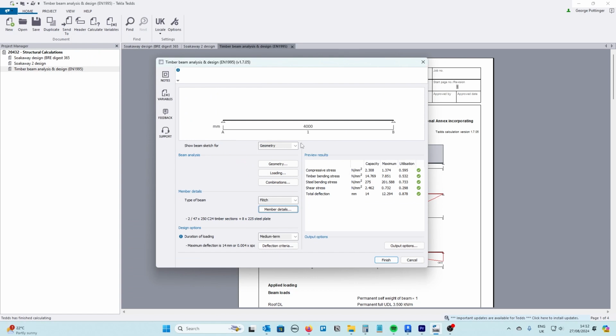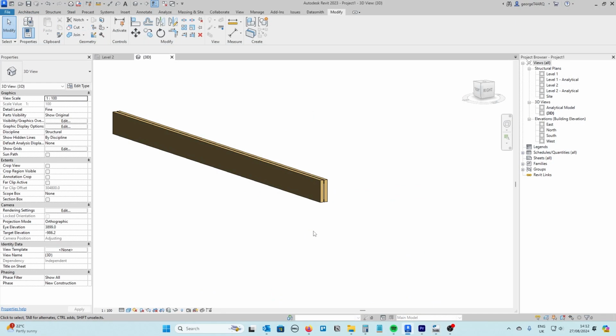So that shows how a Flitch beam can be used with minimal extra structure to provide a nice strong beam over a fairly considerable span. The other advantage is having a number of small elements. For instance, in a loft conversion, you'd be able to manhandle these up into a fairly awkward space much easier than if it was just one solid steel beam.